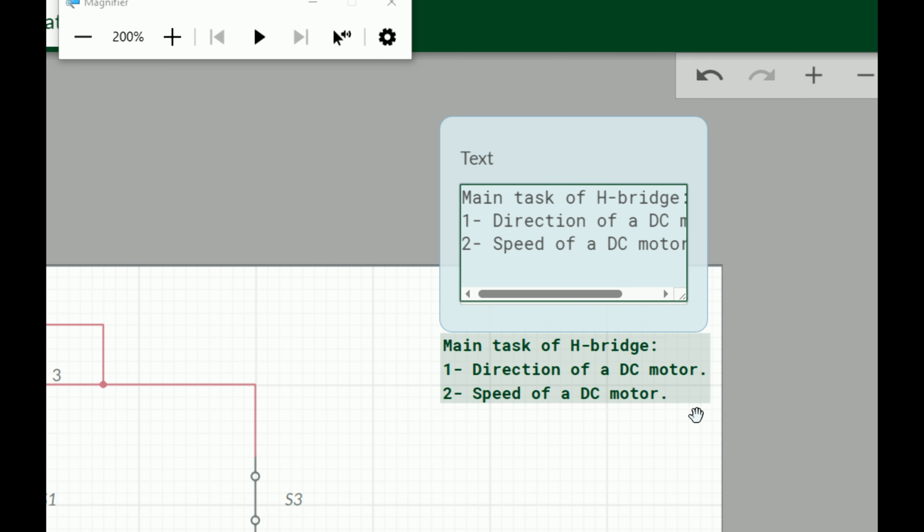Now what I do is make another H bridge. I go to the left and bring in transistors. I bring PNP transistors, 2 PNP and 2 NPN. Now I bring a PNP transistor to replace this. I rotate it so I can make it look presentable like this. I copy this and bring it to this side. I also rotate it like this. Now we are bringing in the transistors.